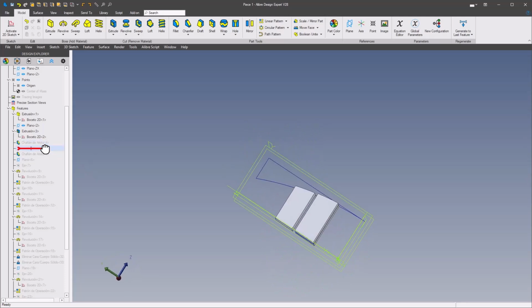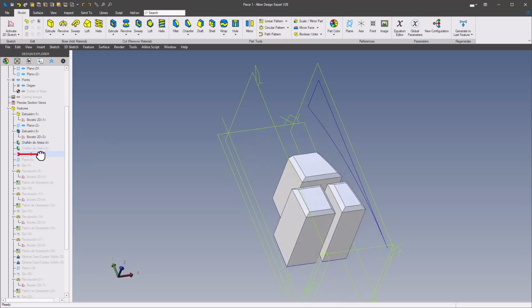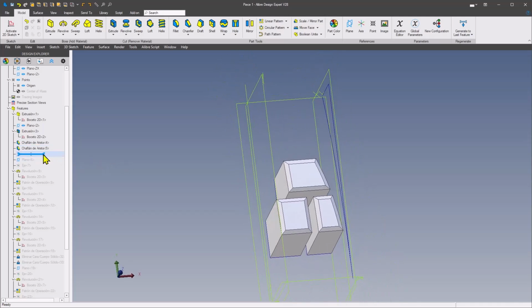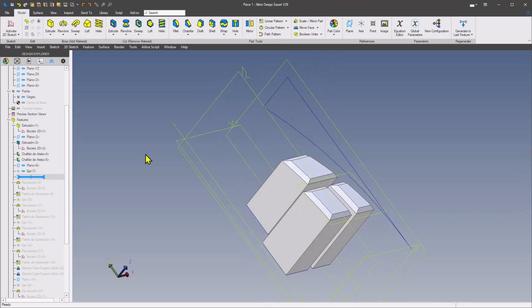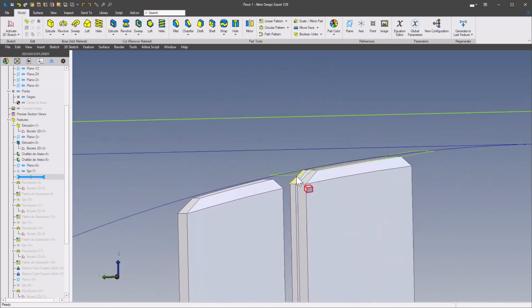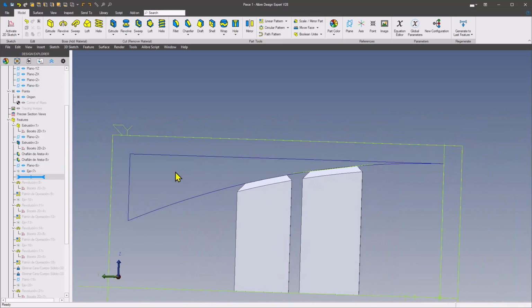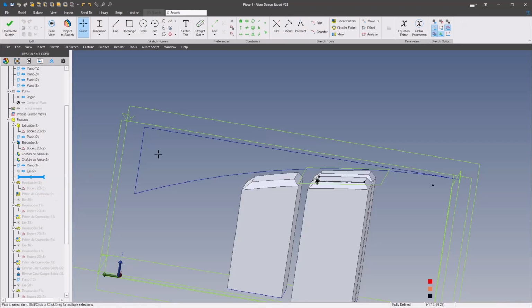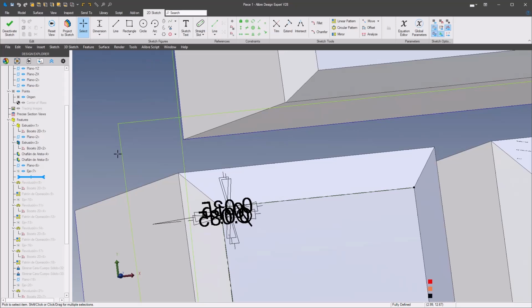So now the next two steps you have here are these chamfers. And I'm not going to do anything with them. But then you've got your first plane here that's going to be tangent to that curved face. And let's take a look at where your first dimple is at. So we'll edit the sketch.